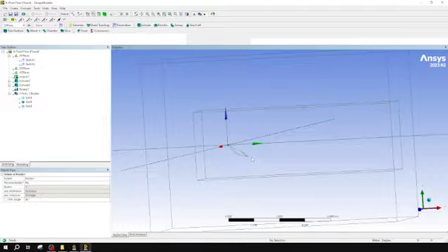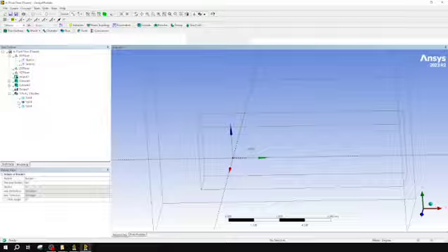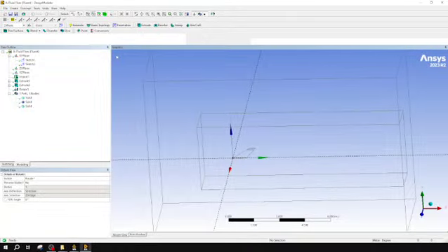Obviously for a wing, 45 degrees is rather extreme. I'm going to actually, for this first one, leave it at 0, because my first angle that I look at is 0 degrees. But the reason I did put this rotate in this early is because it's going to help me in the future make more of these, and I can just kind of copy this entire geometry into the next system.